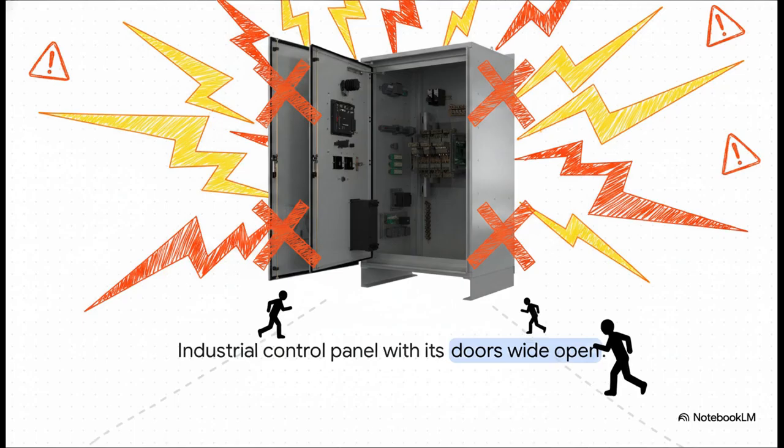Now imagine looking at an industrial control panel with its heavy doors swung wide open. This highlights a critical, life-saving egress rule. If a worker is inspecting that enclosure while it's energized and a catastrophic arc flash occurs, they need to get back and get back fast. Those open equipment doors absolutely cannot act as a barricade that traps them in the working space.